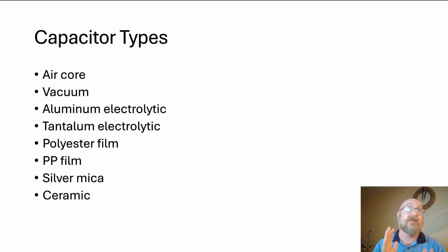recognize that a lot of those are insulators. So the electrolytic ones are the ones that are generally in the polarized category. And that's because the electrolytic reaction that's happening inside of there on charge and discharge is happening between two aluminum plates or tantalum plates. And that can only work in one direction. It won't work in the other direction.